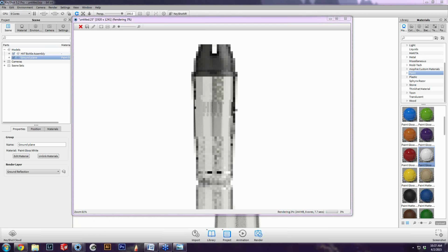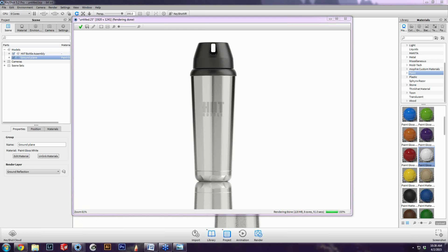So the key to creating stunning visuals is to have great 3D models to begin with. You need to spend time refining the 3D model before doing any KeyShot renderings. A great 3D model doesn't mean that you need to create a robotic arm with 1,000,000 parts in it. What you need is just a model with each individual part named and organized properly in the assembly. Again, add color appearances in your 3D model to separate the materials in KeyShot. You might want to pay attention to even the smallest fillet, chamfer, and draft angles, because these kinds of details could enhance your visual renderings and make the images stand out.